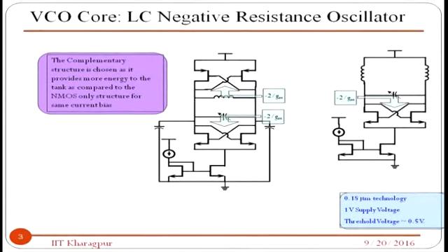Okay. So, what is the basic principle of operation of any oscillator? If you look from the active side, you will have a positive impedance, and if you look from the other side, that is from the tank side, and see the active side, you will get a negative impedance. Positive impedance dissipates energy, and negative impedance actually creates energy. So, oscillation goes on, and that is why when the Barkhausen criteria is satisfied, you will have sustained oscillation